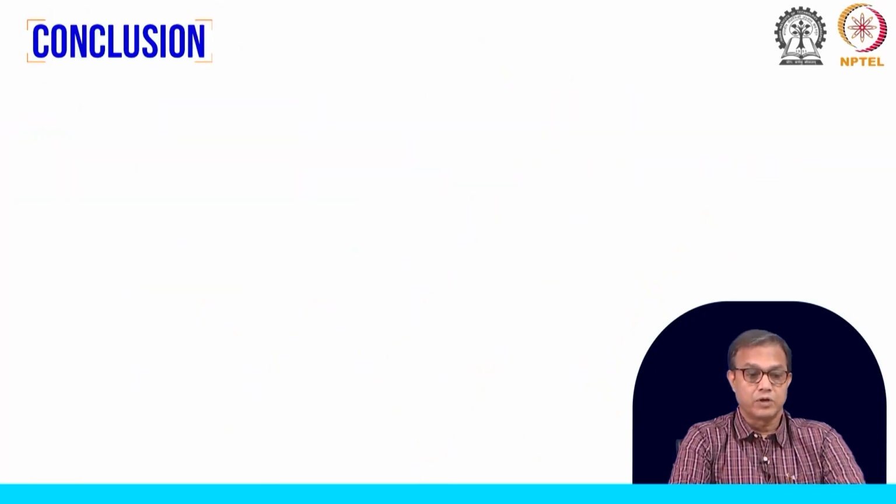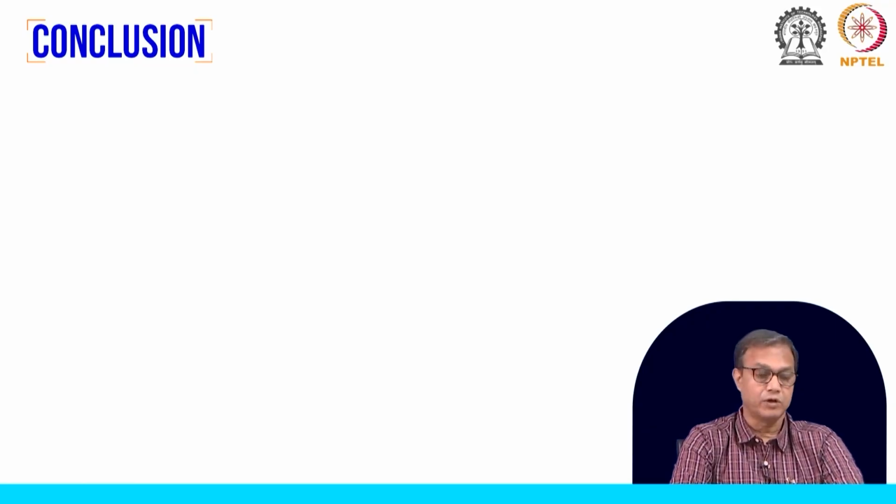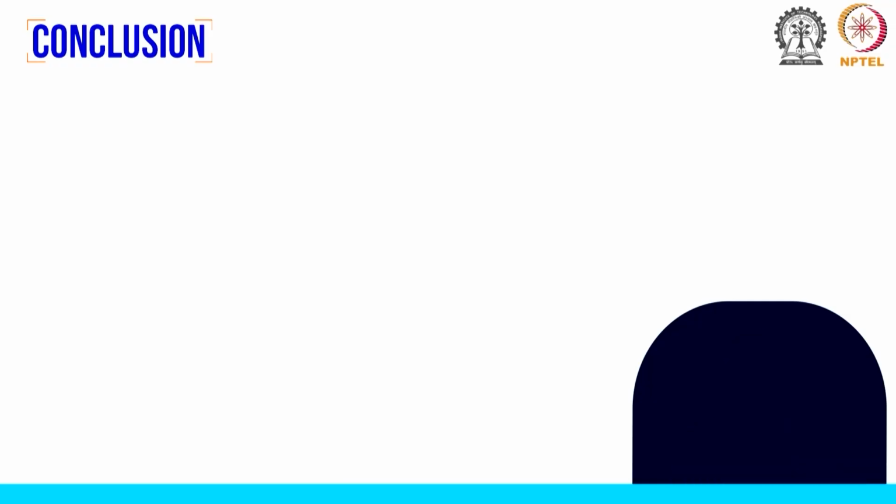So, the conclusion: we have learned about the so-called conventional techniques, the process features of steam reforming, autothermal and partial oxidation. So, in future whenever needed, we will talk about these processes. You have to keep in mind the typical temperature range and the basic needs of this kind of processes. So, that is about hydrogen production at the moment.